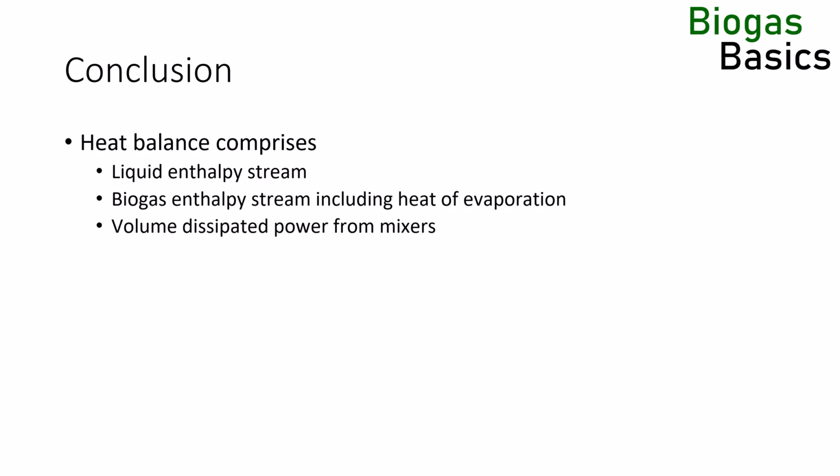The energy input of the digester mixers must be considered in the heat balance. Use only the active power of the mixers. The mixing energy heats up the digester. The heat of reaction can be a large term contributing to the digester heating. The exact heat of reaction can be calculated from the stoichiometry of the biogas process, which must include the biomass formation. The heat loss cools the digester.